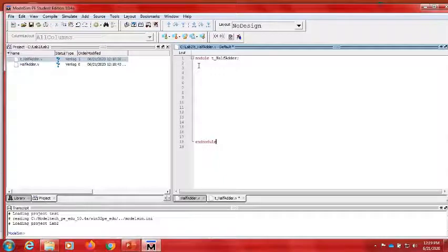Now the next step is you have to define your inputs as reg and outputs as wires that are being used for the communication with the main design that is under your test. So we are using the keyword reg, X and Y variables as registered inputs, and wires, sorry, the keyword wire, S and C, semicolon.